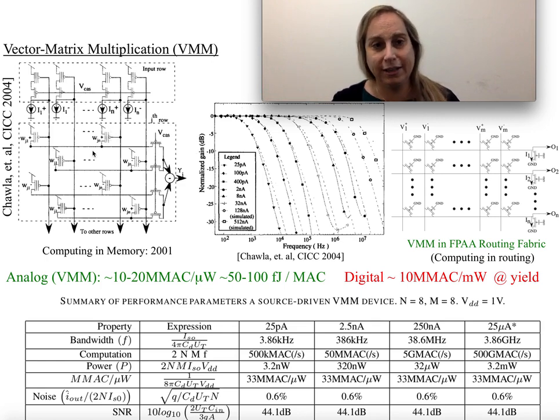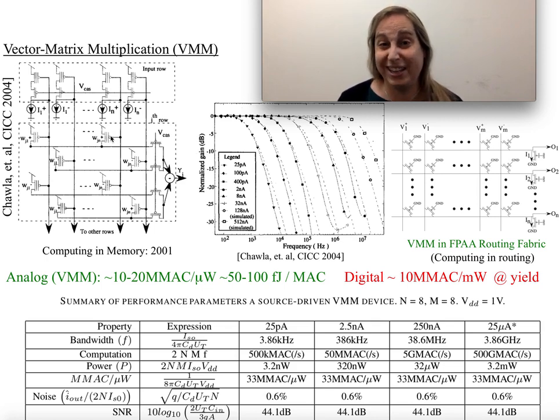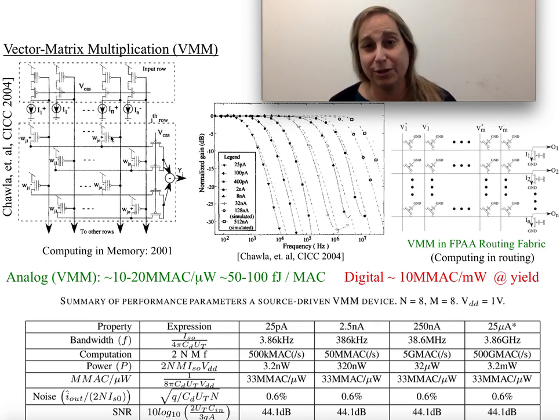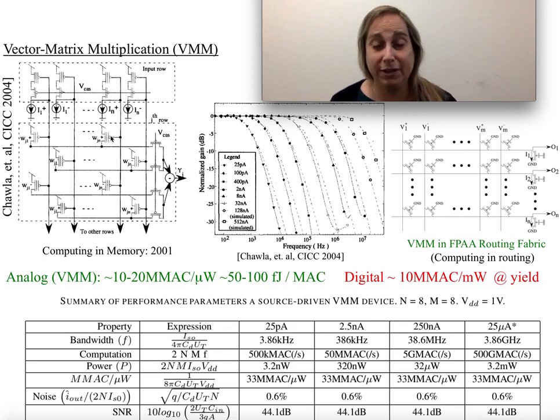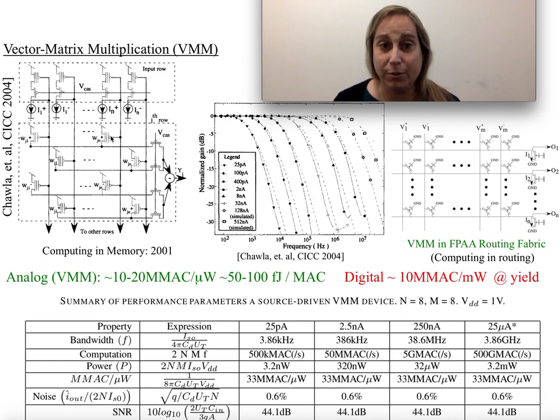Once you get that right, it's easy to think about how you do multiplication. As in this original structure, the difference between where these two floating gates are, and effectively their new, say, bias current or threshold, they have two different values that make it look like a current mirror with different ratios. It's really done by moving the flat band or threshold voltage, but all that works. What you realize is you have a current mirror of a certain gain, which is programmable, i.e. a multiplicative gain.